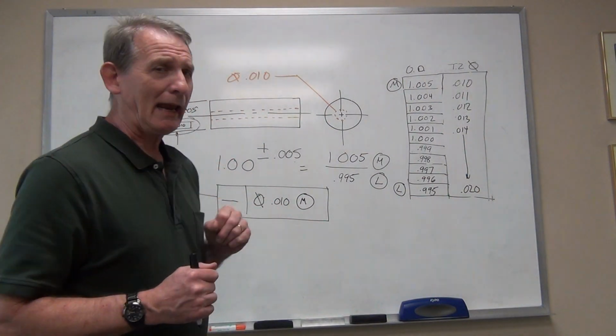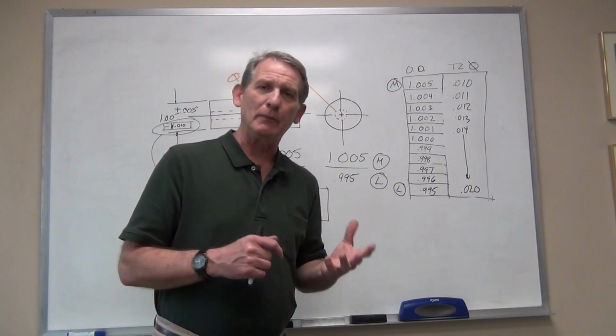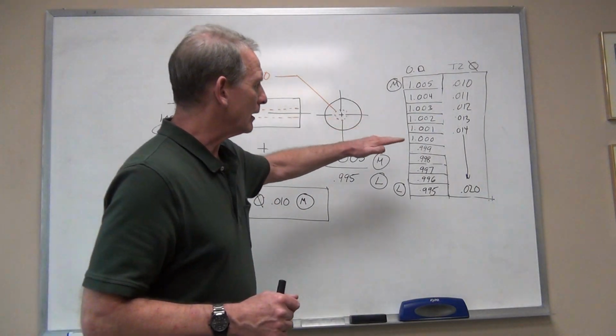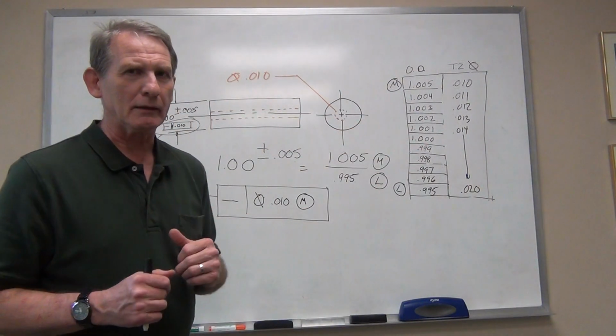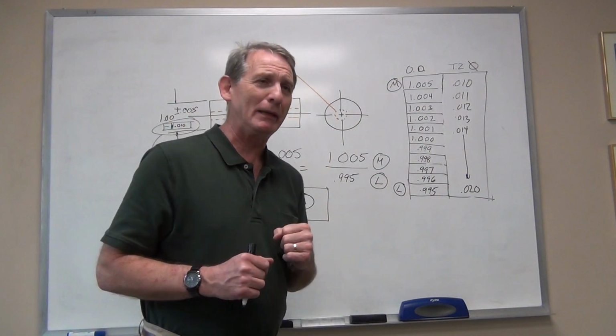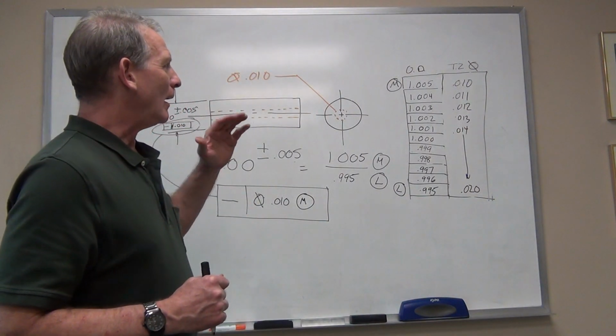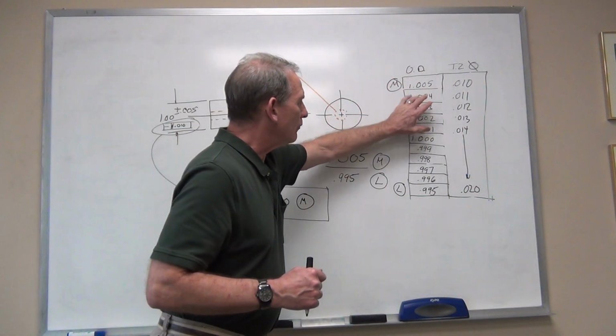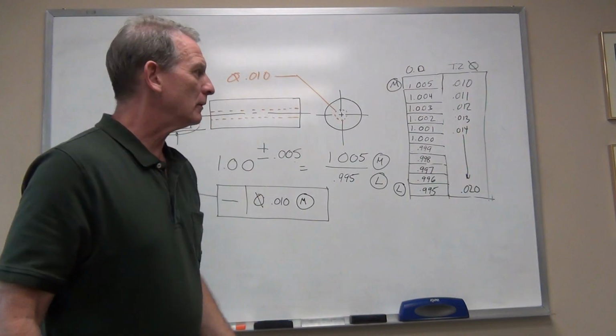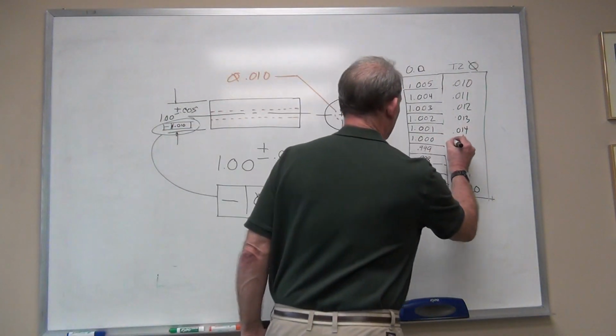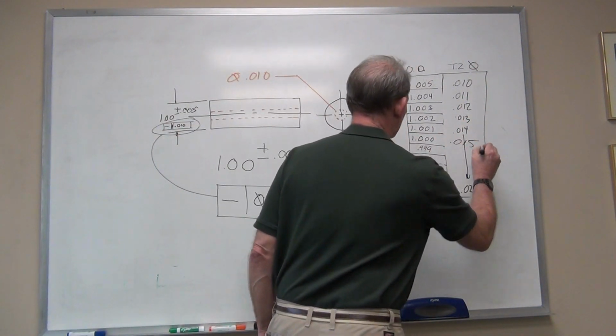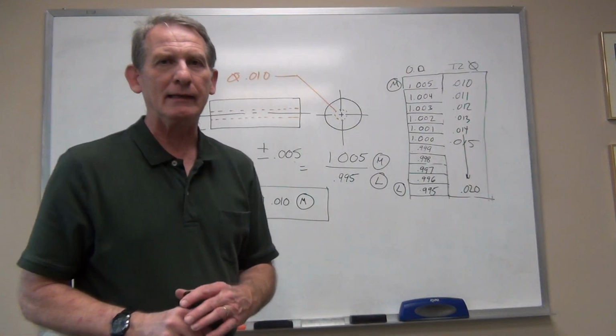So how do you play this game? Well, you pick up a part, you measure it, you say, well, this one hit right at split limit. This is exactly where I want to be. I have taken 5 thousandths off from maximum material condition. I know then that my straightness tolerance zone is 15 thousandths in diameter.